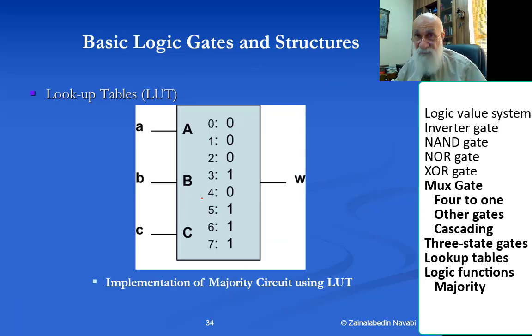Earlier we talked about FPGAs, or field programmable gate arrays. Field programmable gate arrays have non-dedicated logic functions that you can program to make them do anything you want. Therefore a multiplexer is good because you can turn a multiplexer into whatever you like. Another structure that you can turn into whatever you want is what is called a lookup table.